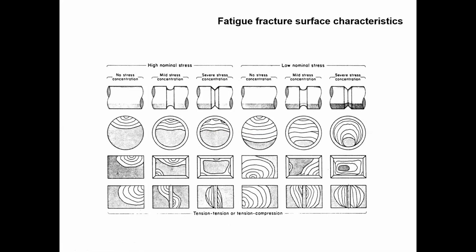When a part fails after fracture, what does the surface look like? You can observe the cross sections and tell what the reason is. Is it over stressing, or is it high stress concentration? You can also count how many stress concentration points there are, and explain by observing that particular cross section. So we already discussed this one.